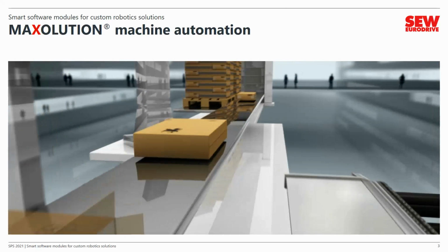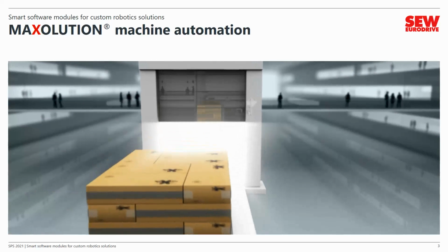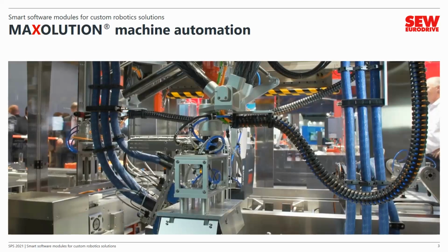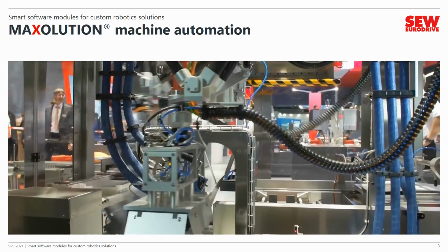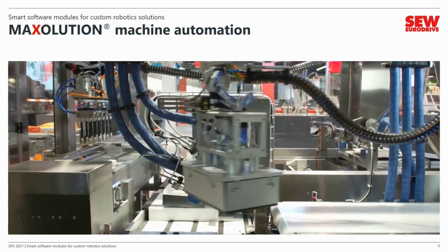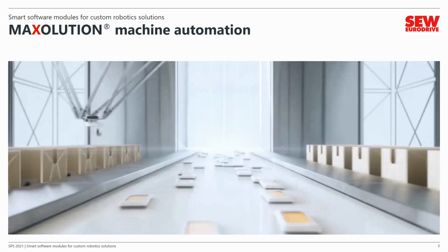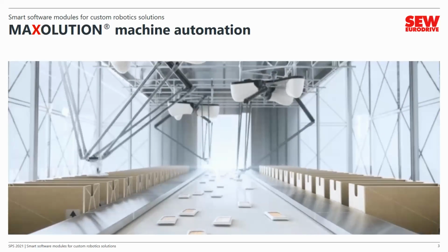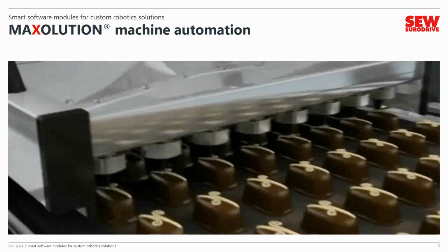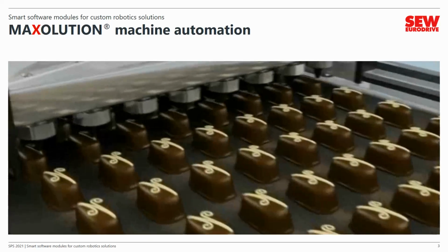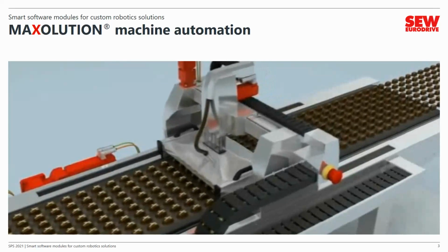In addition to conventional gantries with 2 to 5 axes, SCARA robots or single column palletizers with 3 or 4 axes are also frequently used. The advantage of the parallel kinematics shown here is their stiffness at relatively low dead weight. We support them from 2 to 6 axes. If fast speeds are crucial, the tripods with 3 to 5 axes stand out with a large work envelope. Our solutions are also perfectly suited for decorating food and processing workpieces.